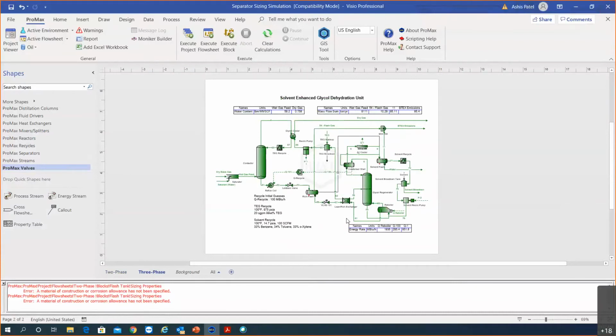In a wet gas, after you go through an amine unit, typically that gas, once it's rid of its H2S and its CO2, is saturated with water, and that will also need to be removed. So it gets sent to a glycol dehydration unit where it's brought into contact with the glycol solution to pick up the water and reduce it to pipeline quality, which typically means somewhere around 2 to 7 pounds of water per million standard cubic feet of gas.